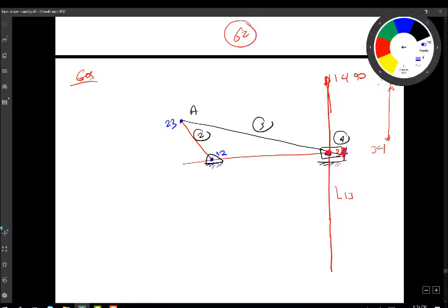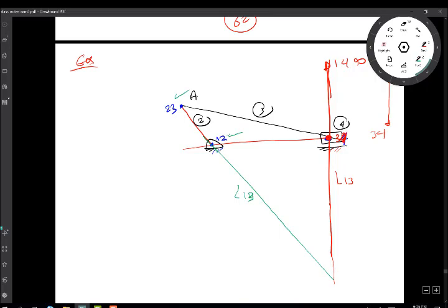So I can come to the problem from the other end, and I can say, okay, this is point 1, 2, and this is point 2, 3. Common number is 2. Missing point is 1, 3. And I can draw a line just along this here, and this will give me another locus for 1, 3. Okay, so the two loci intersect at a point, and this point is going to be the 1, 3 we're looking for. So this is 1, 3, meaning that this is the pole of link number 3,